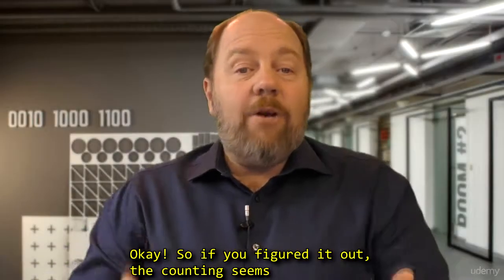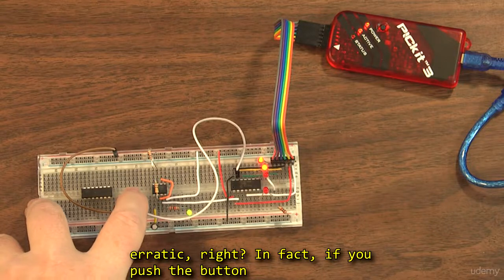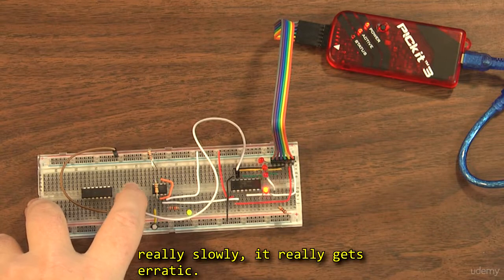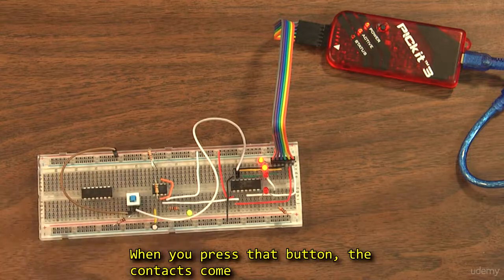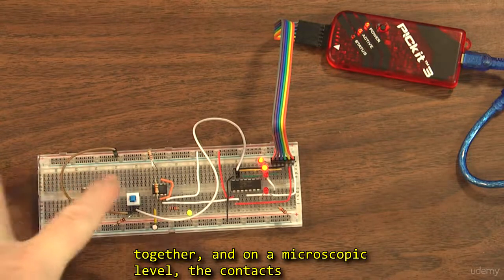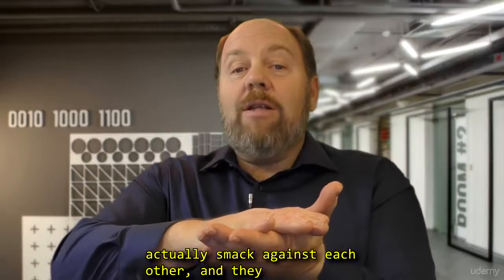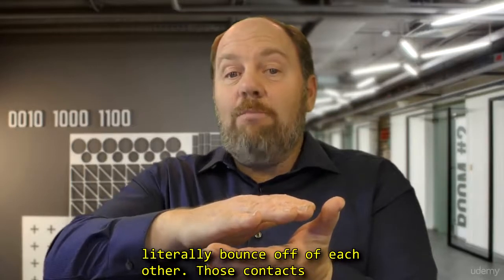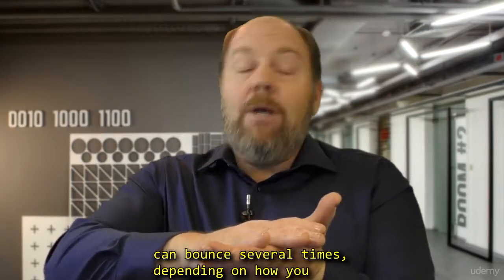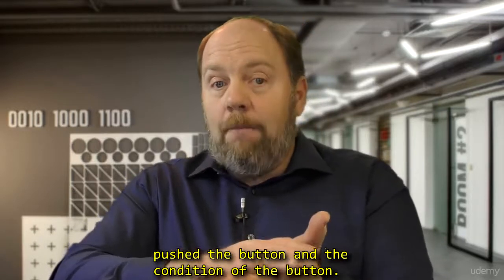Okay, so if you figured it out, the counting seems erratic, right? In fact, if you push the button really slowly, it really gets erratic. So here's what's going on. When you press that button, the contacts come together, and on a microscopic level, the contacts actually smack against each other, and then they literally bounce off of each other. These contacts can bounce several times, depending on how you push the button and the condition of the button.